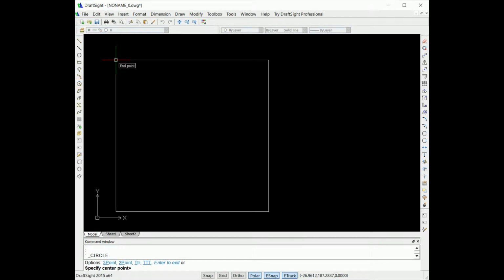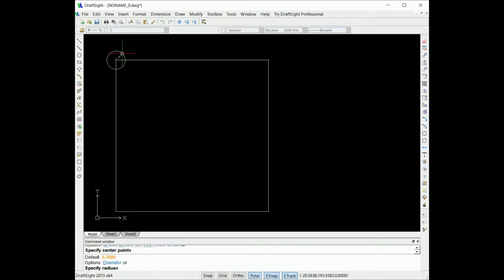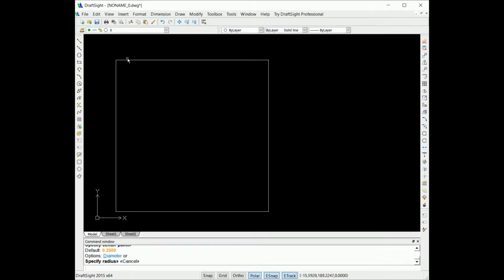And as you remember from last time, if you want to get a reference point for your relative positioning, you just pick what reference point that you want. I want that corner up there, and then before I click, I'm going to hit escape. Now it has marked that spot as the last relative point I've picked.